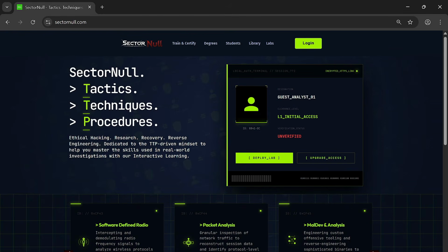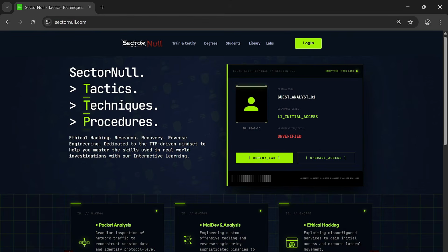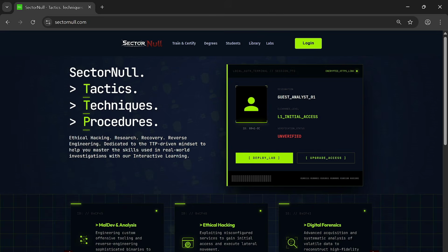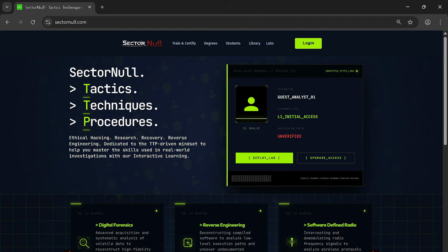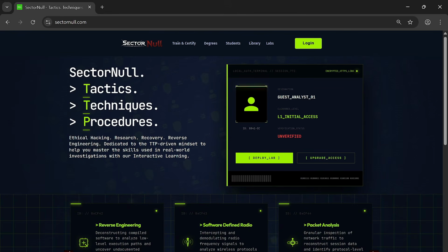At rest, both CAN high and CAN low sit at about 2.5 volts. That is your baseline. When data is transmitted, CAN high jumps up to 3.5 volts and CAN low drops to around 1.5 volts. They move in opposite directions, and that differential signaling is what gives the controller area network its noise resistance.